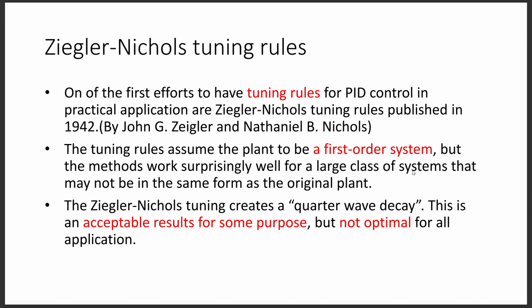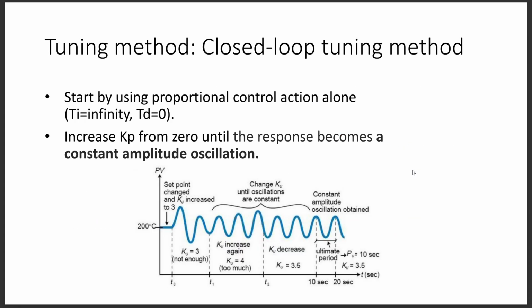So what the Ziegler-Nichols method creates is a quarter wave decay, which is an acceptable result for some purposes, but it's not always optimal. So it's a good method, but it's not necessarily the best design you can have. It depends on the application.